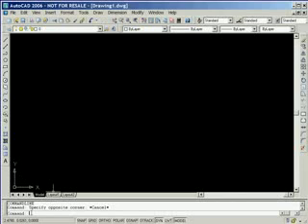Autocad also allows commands to be typed in from the keyboard. When this is done, your typing shows up in the lower portion of the screen called the Command Prompt area. Autocad also uses this region of the screen to display prompts, so we'll need to keep an eye on this area of the screen.